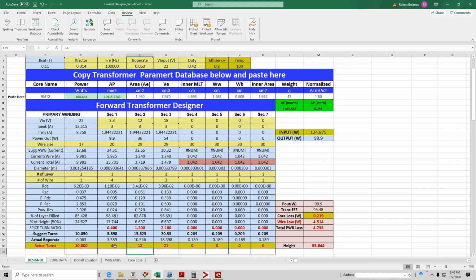And again, this one, if I go to 3, I won't get 3.3, I'll get 3.4. But if I go to 4, most supplies can handle a little bit extra. So in here, I have 89 millivolts above that. So I can live with these voltages.